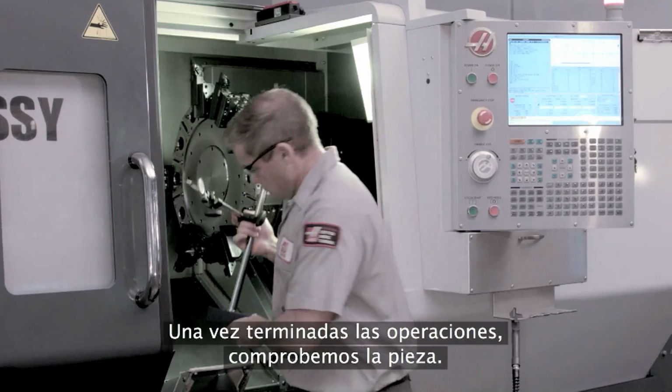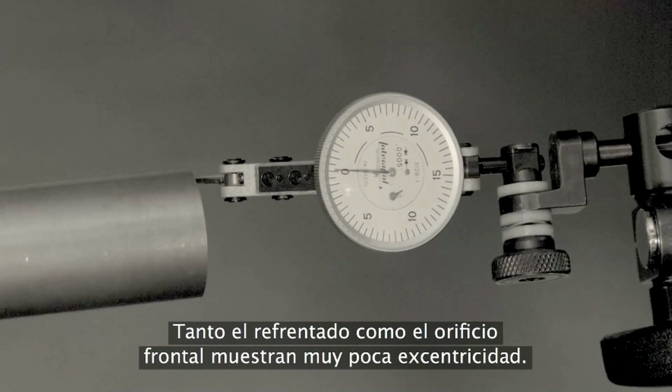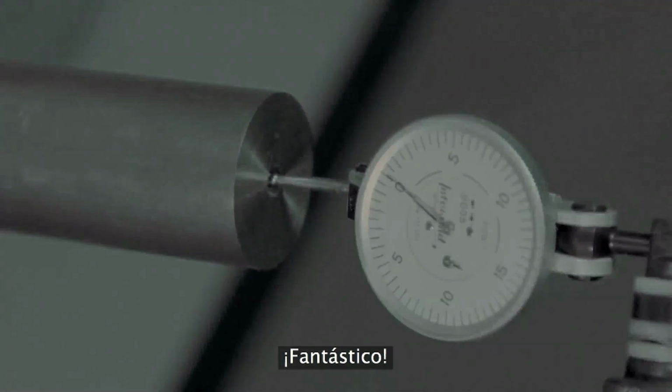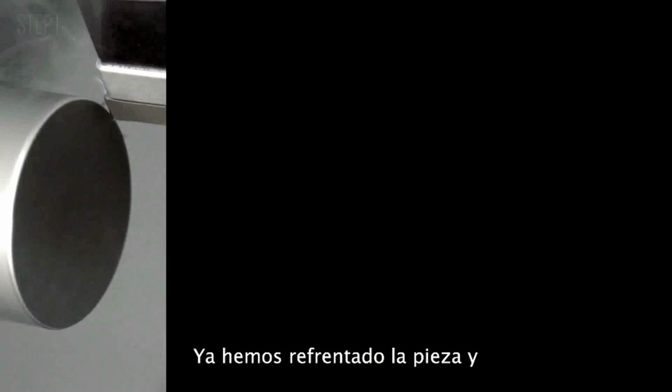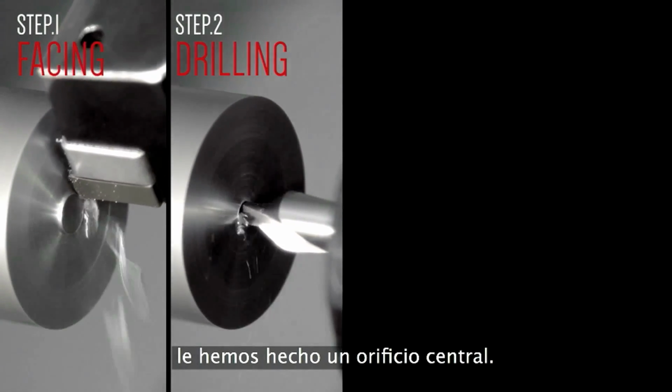With the facing and drilling complete, let's check our part. Both the face we just turned and the center drilled hole have very low runout. Great! Okay, so we just saw the part get faced off and center drilled. These operations start off our program.